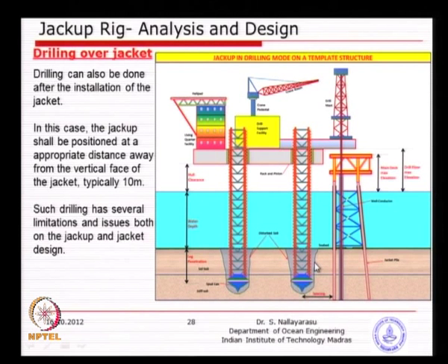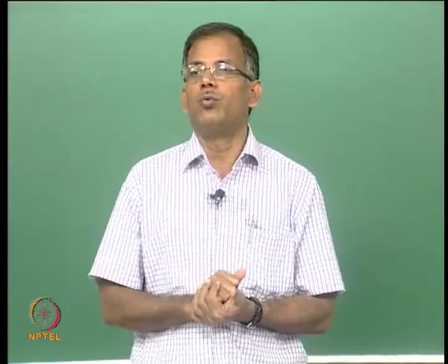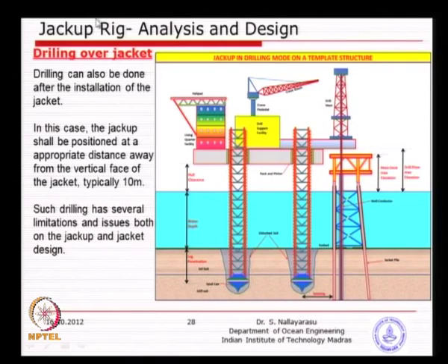So, now you need to see that the wider you make the spacing, the better for the soil, but the wider you make it is not so good for the drilling, because the cantilever cannot go too far. Of course, you can design this cantilever girder strong enough, make it very big, but still there is one potential problem, which is stability. The whole weight of this mast plus this whole thing could be a few hundred tons. The longer you go away, the stability of the system is in question, and many times that will become a problem depending on the spacing between this leg and that leg.